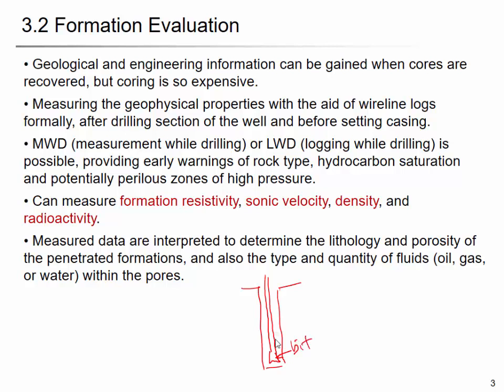And then in this section, you install some sensors and measure the physical values using these sensors. It's called the logging, and you can measure the formation resistivity and sonic velocity and density here and the radioactivity.